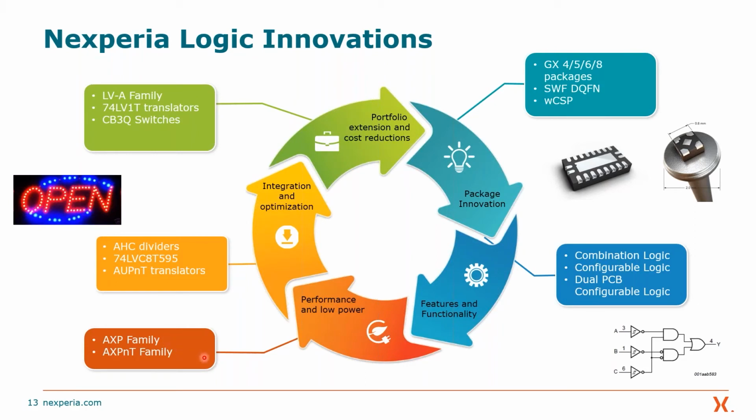Other things are, in the lower left, you need to change the family type, the process. The process family follows the microprocessor. Back in the 1960s, which were actually RTL level devices running at 15 volts or higher, the logic families needed to be 15 volts. Microprocessors, when they were 5 volts, needed a 5-volt logic family to support them. Then 3.3 and 2.1 and 1.2 and 1.0.